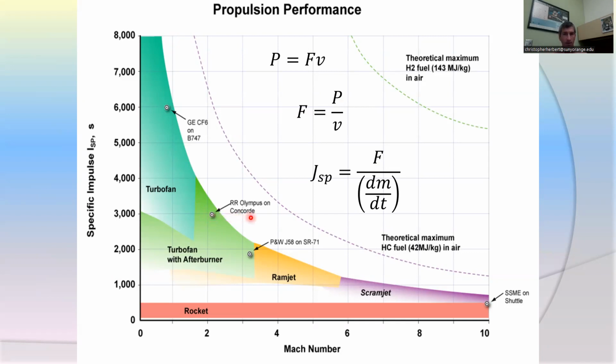And we see this with supersonic transports such as the Concorde, okay? Or on the SR-71, it gets even worse here. That is the Blackbird, the fastest plane, where our specific impulse drops even more. For the space shuttle engines and the engines that are used on Artemis, we can see that once we start traveling up to Mach 10, this specific impulse becomes much, much less.